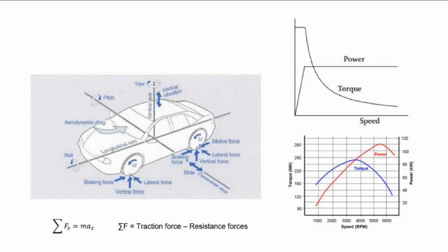In general, the drive system limits traction capacity at high speeds, while adherence imposes a limit when running at low speeds. If you use a vehicle, you know the low speed and the speed and torque relationship. We are using a gear for adjusting the speed and the torque.